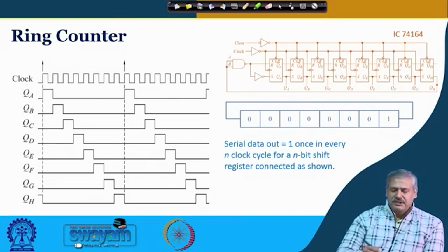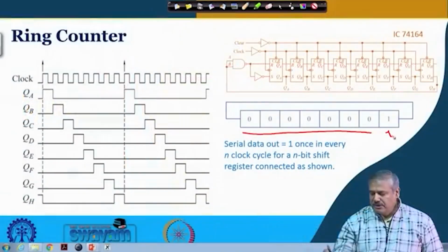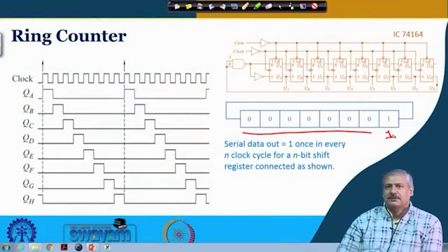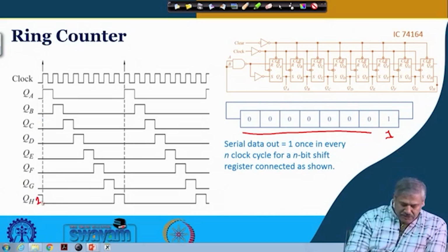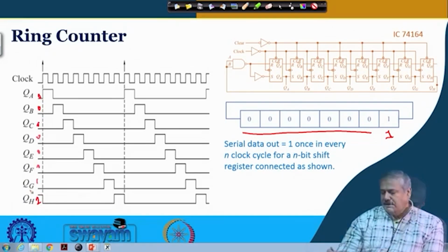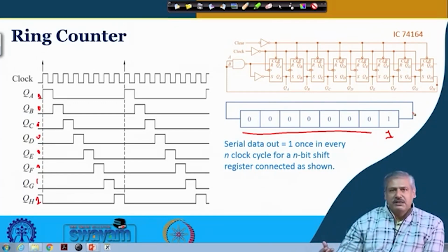So, when we talk about this shift register as a counter, we are using the shift register again in a feedback mode, and in this case, unlike the sequence generator where we are putting in a specific sequence, we are putting in, in one example, all zeros and only one value is 1. Okay. So, this is how we are starting. So, this is 1 and all these values are 0, and then one clock trigger is getting counted here, as I said.